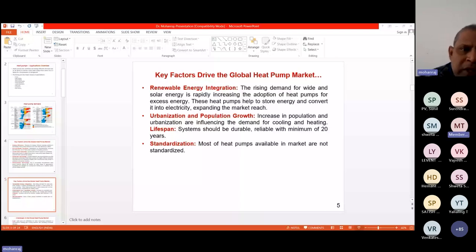Yes. So these are some of the refrigerants commonly used in heat pump systems. The earlier CFCs were shifted to HCFCs, and HFCs were shifted to HFC refrigerants. HFC refrigerants are shifted to hydrocarbon refrigerants, hydrofluoroolefins, carbon dioxide, and mixtures, and hydrocarbon mixtures. So it is shifted like this, but these hydrofluorocarbons are interim options, and we are going to phase them out soon.